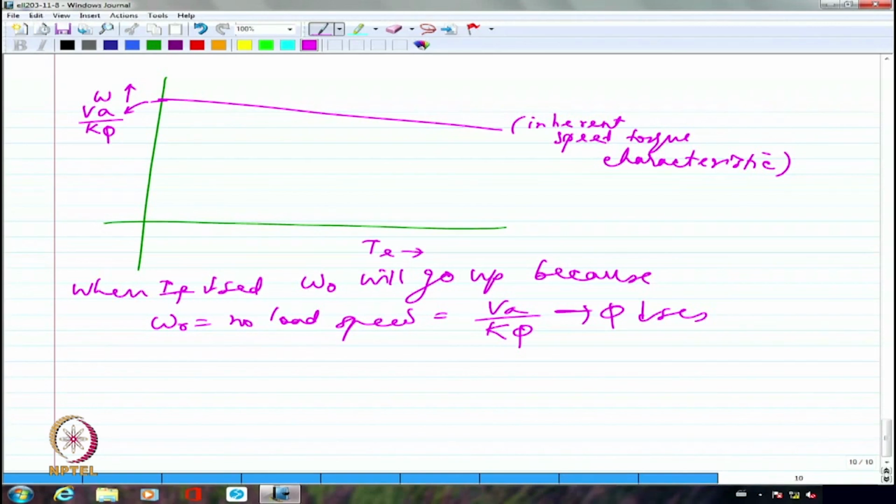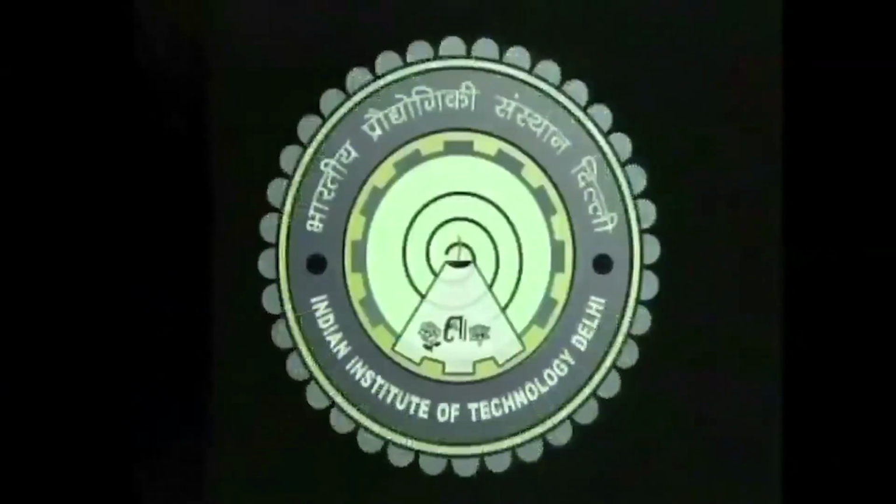If the speed increases, originally I had K omega phi. Phi had decreased. Now the speed will hit that value such that K phi omega comes back to its original condition. So invariably, when you reduce the flux, you will see a transient increase in the current, which will eventually settle down at the original value itself. But in the process, if IA settles down to the original value, the torque has to drop, because torque is K phi IA. Right?